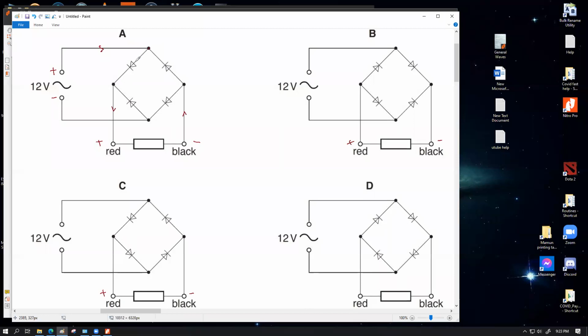So it is going to flow through this path, reach up to here. Can you follow? If you miss out at any point, stop me because you have to understand this thing. So current cannot go through here. Current is flowing through this diode unrestricted, coming to here. This is providing a restriction, so current cannot flow through this path.